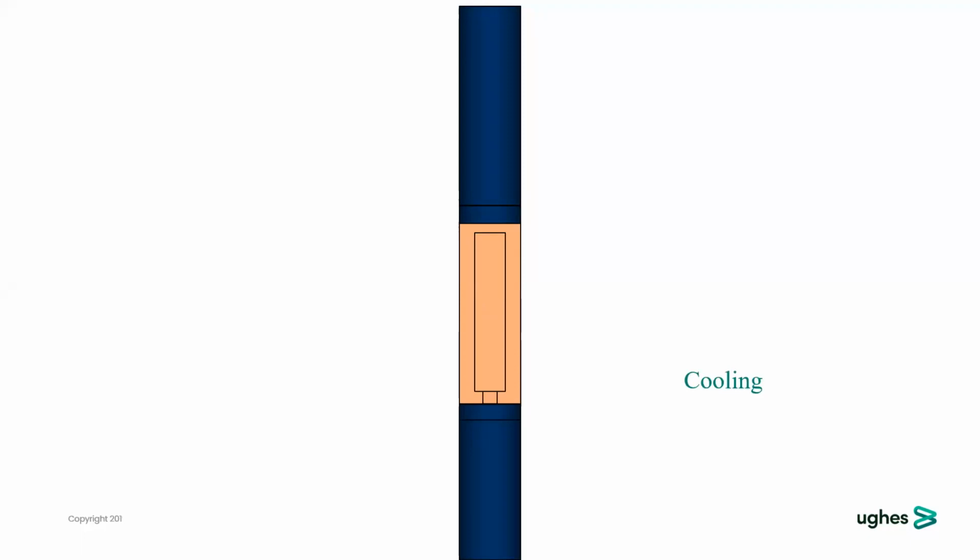And that bag chamber will not be affected by deviation. So this is the replacement, or the most proper plan, for having the seal chamber on a deviated well. And that is the second function of the motor seal, to allow for expansion during operation. That bag will be expanded during heating and will be contracted during cooling.